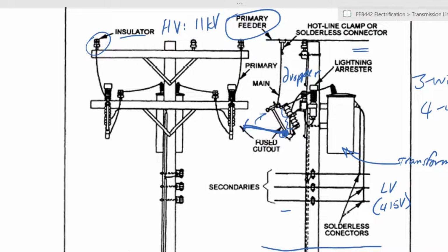Now, one thing that is not indicated in this diagram is usually below the transformer, you would have a set of fuses for the secondary low voltage lines. Before the low voltage exits or leaves the transformer, you could actually disconnect them. And those are in the form of physical ceramic fuses that are mounted 1 per phase below the transformer itself. Those ones are very easy to see.